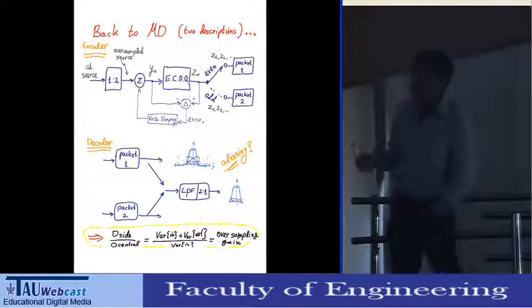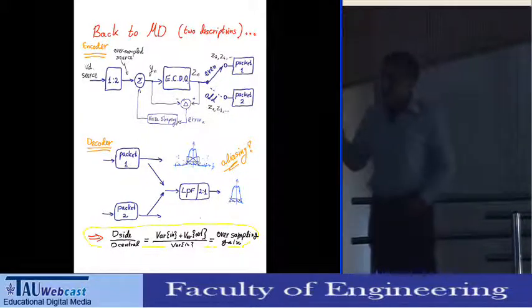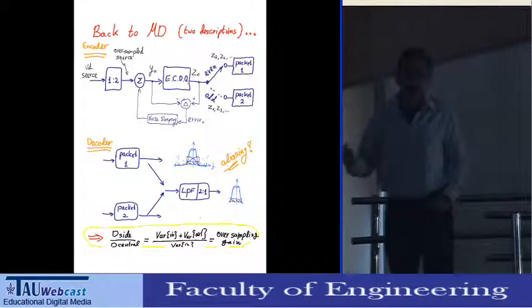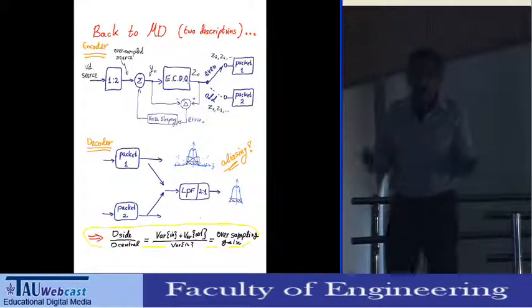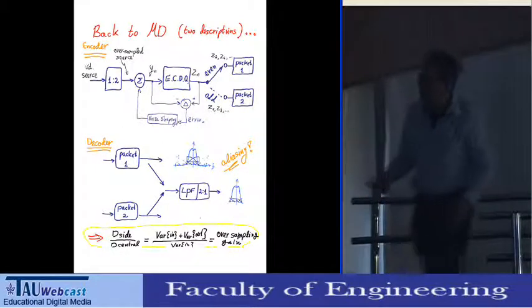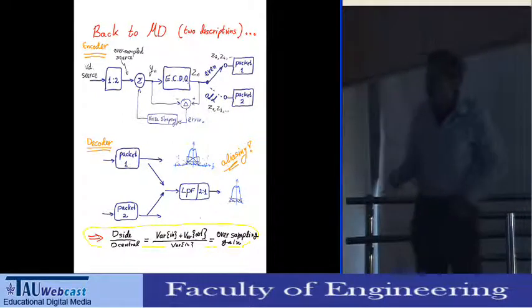I'm getting twice what I need. But let's see what happens with the quantization noise. As we showed before, it is more like a high-pass noise. If I'm getting only one packet, it is equivalent, from the noise point of view, to doing subsampling or decimation without doing anti-aliasing filtering before that. So I'm getting the folding of the spectrum of the noise into the in-band, and I'm getting high distortion. If I'm getting both packets, I can do the perfect low-pass filtering and forget about the high-pass noise.